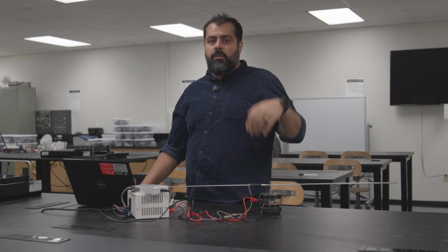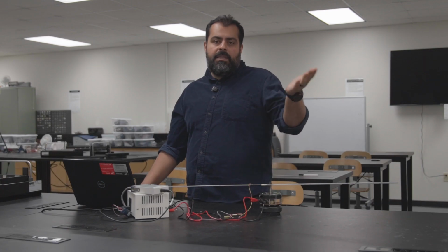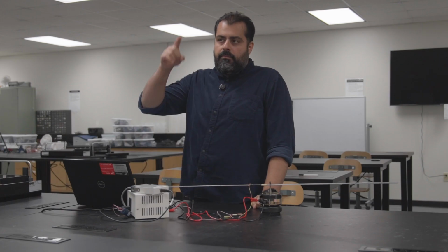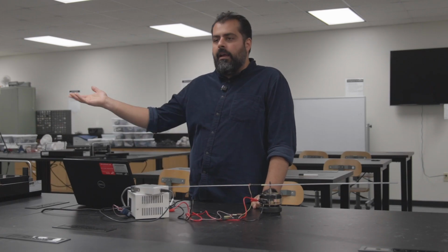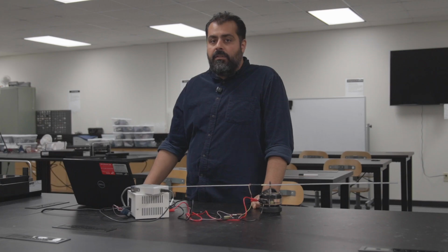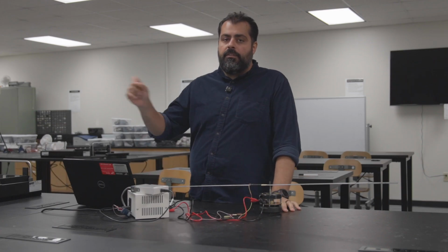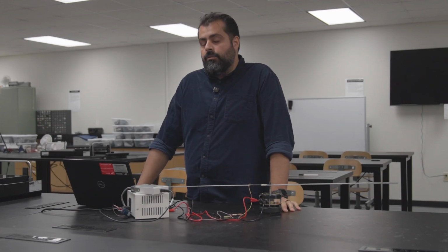There's a first one, but it can be the second, third, or the 10th wave and the 100th wave. It doesn't really matter which one you choose. You just choose two, find the amplitude of the two, and count the number of periods in between the two amplitudes, and then you do your calculation.